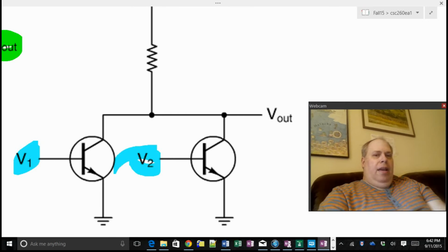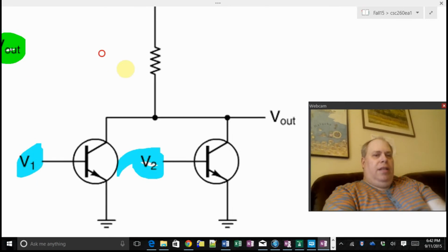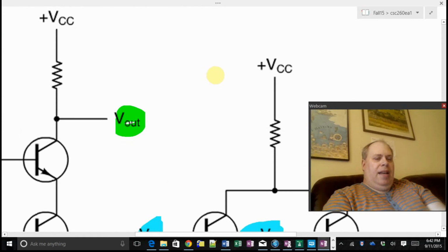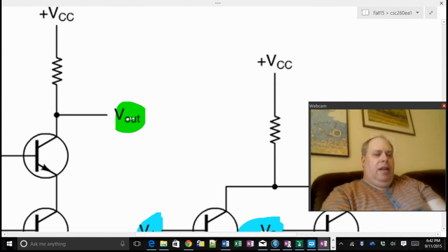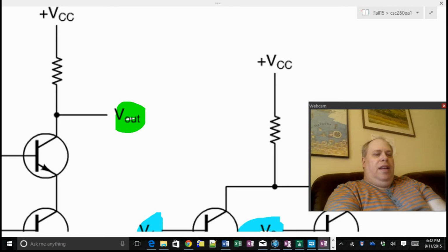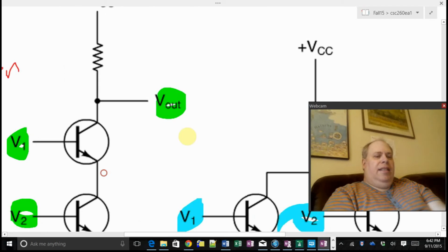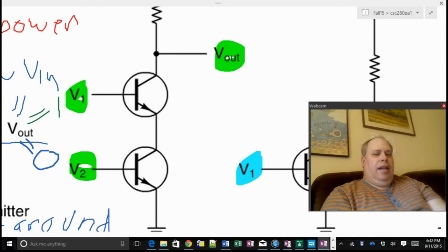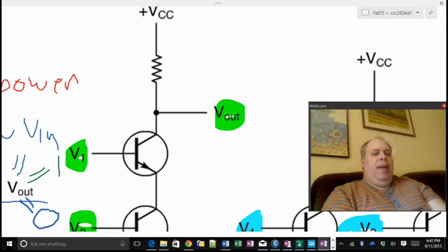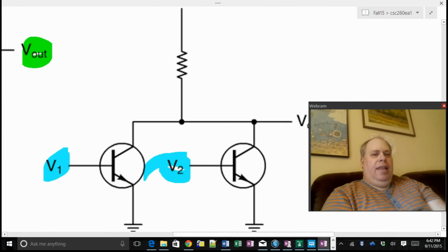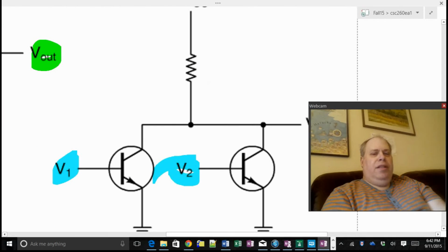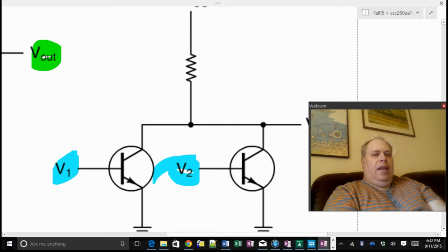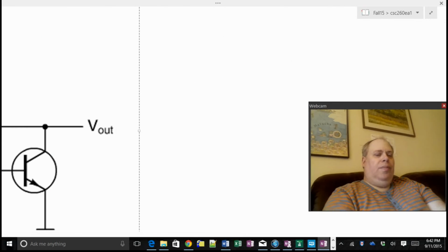By the way, when using complementary logic in CMOS, what we end up doing is there's a series circuit, and the complement is a parallel circuit. And the opposite of this parallel circuit will be a series circuit.